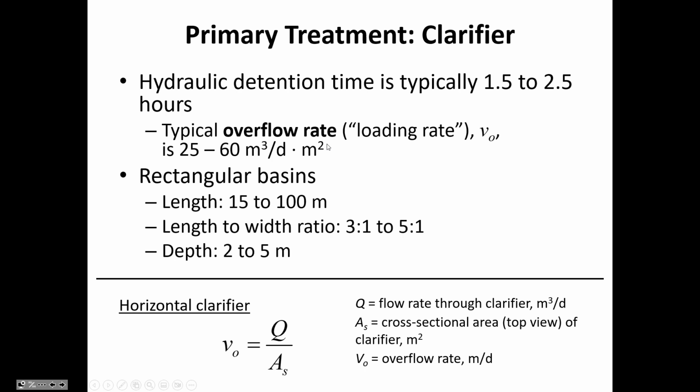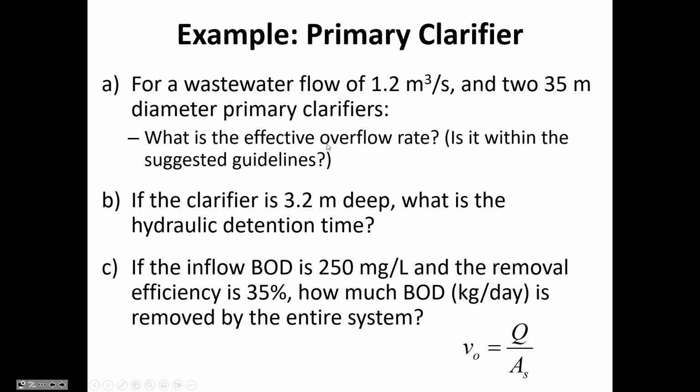So let's see in this case if we load 1.2 cubic meters per second into these two 35-meter diameter clarifiers. Are we within that range? And then you can see in part B we want to calculate the hydraulic detention time.